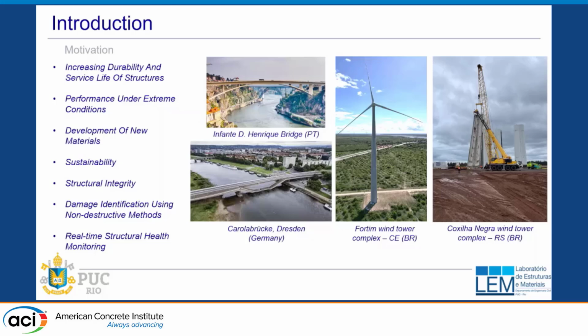But the fact is that it was being used for more than 40 years or so, and there was no redundancy in the system to distribute the load. There were large sections of the concrete that were connected without any reinforcement, because in the negative moment region, they were depending completely on the post-tensioning. But the report is going to come out soon.